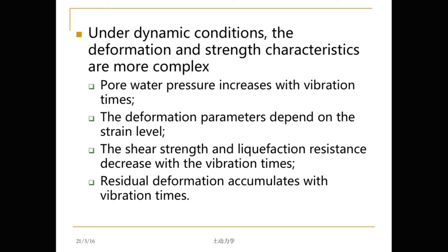In the vibration, it will cause the increase of the pore water pressure, or generate excess pore water pressure, and it causes the decrease of the effective stress. Then the decrease of effective stress leads to the decrease of shear strength, and even liquefaction occurs.